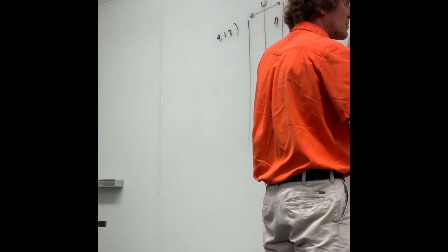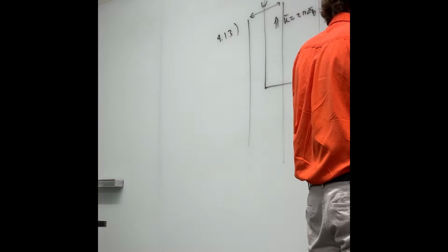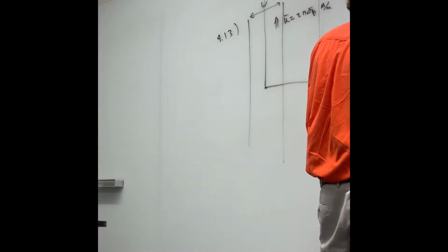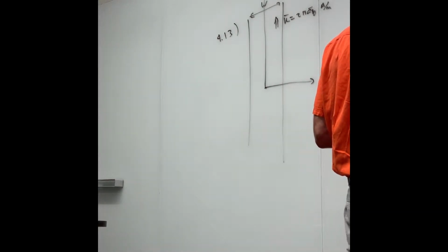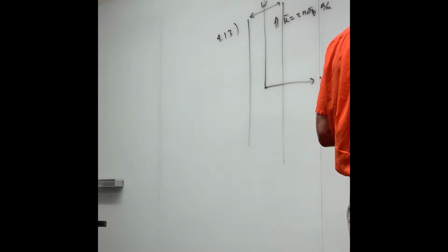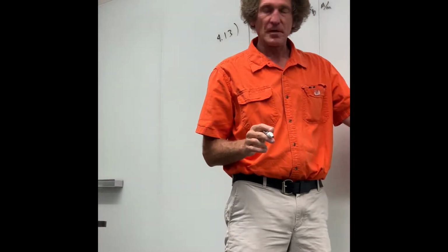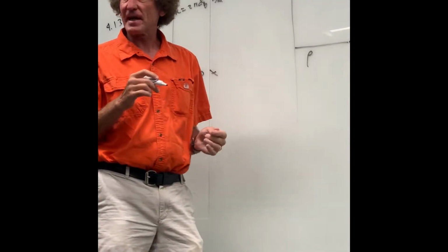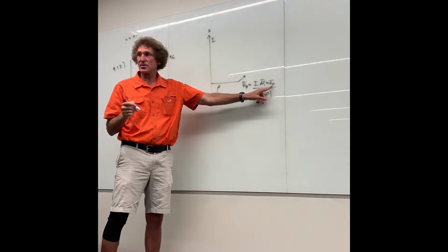Then if I come out a radial distance rho from here, I'm going to get an H field, and that H would be in the phi direction. That would be I dl cross a_rho over 2 pi, divided by the magnitude of rho. Now, I'm doing this for a reason. You're used to seeing just a_phi here, but if the current is on the z-axis, you need to get the direction by doing the cross product. Does everybody follow me on this?